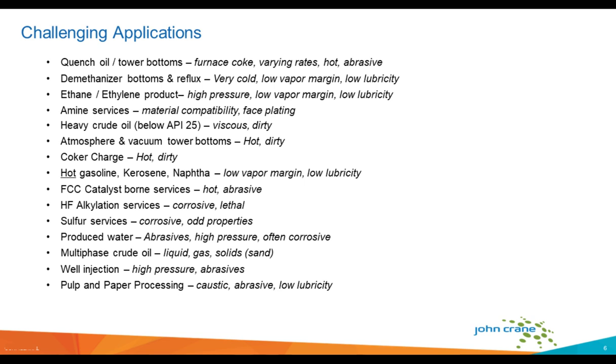Now, depending on the process industry, i.e. the oil and gas, chemical process industry, wastewater, mining, etc., each will have some challenging application that require special design and or sealing solution. Some of these applications, I'm not going to list all of them, but you have quite a few of them. You have quenched oil, tower bottoms, where you have coking problems, demethanizer bottoms or reflux or deethanizer reflux pumps, or very cold, low vapor margin and low lubricity. Ethane or ethylene were very high pressure and low vapor margin as well.